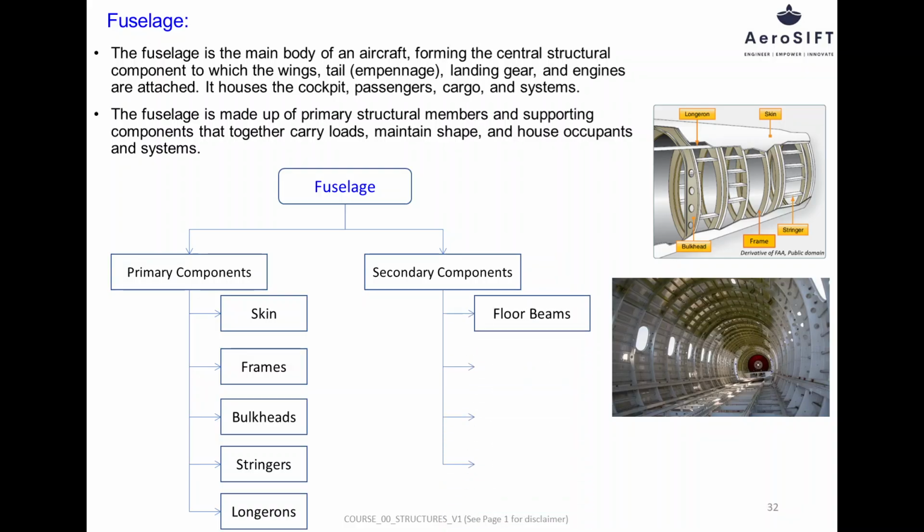Secondary components of fuselage. Floor beams are structural members that support the cabin floor and carry loads from passengers, cargo, and seating systems. These loads are transferred through the floor beams into the fuselage frames and skin. Floor beams also contribute to the overall stiffness of the fuselage.